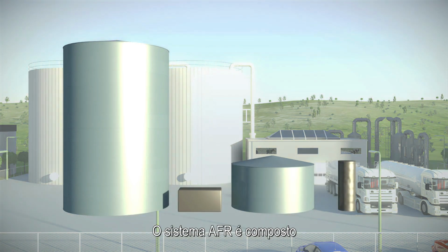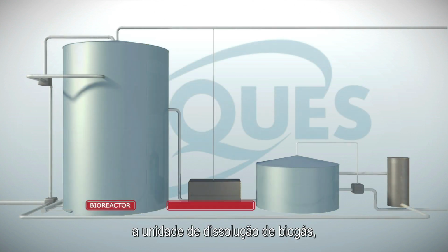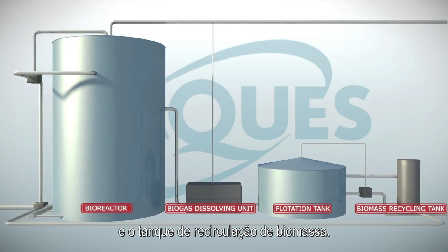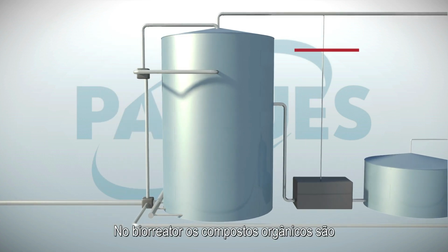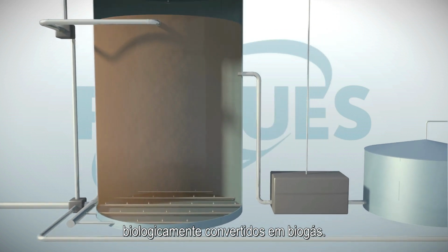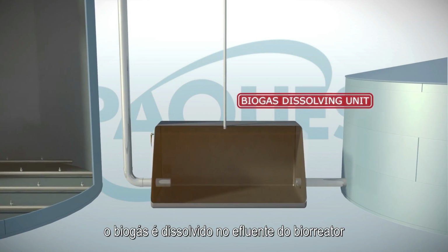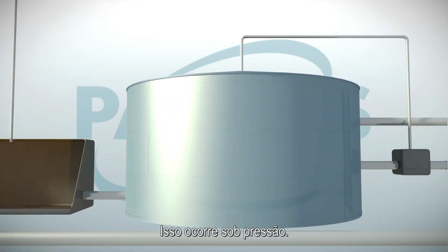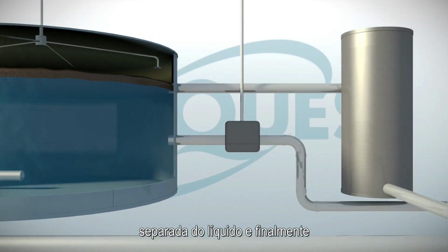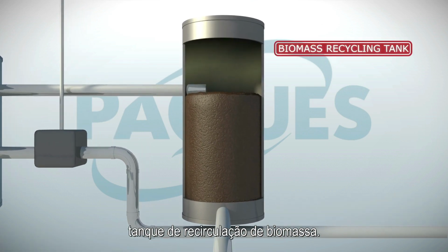The AFR system is composed of different units. The main units are the bioreactor, the biogas dissolving unit, the flotation tank, and the biomass recycling tank. In the bioreactor, the organics are biologically converted into biogas. In the biogas dissolving unit, the gas is dissolved in the effluent of the bioreactor. This takes place under pressure. In the flotation unit, the biomass is separated from the liquid. And finally, the separated biomass flows into a biomass recycling tank.